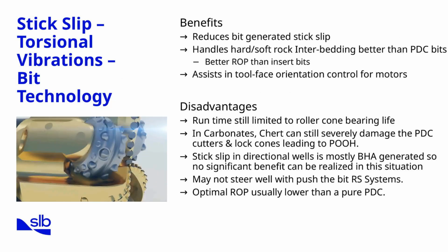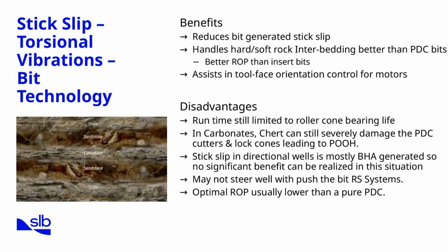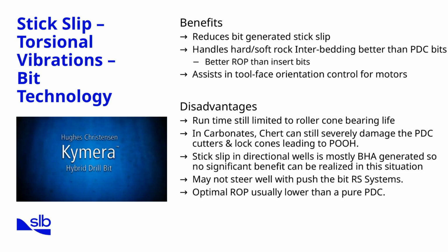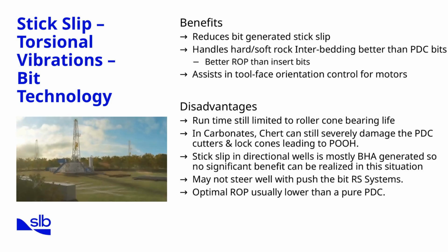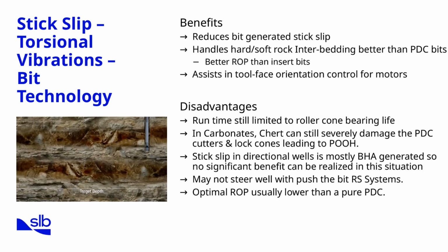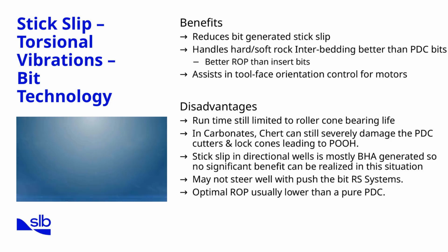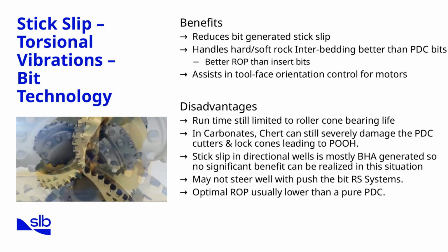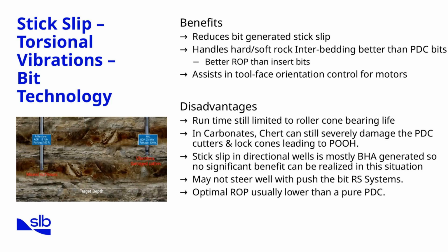First bit that successfully combines PDC and roller cone bit technology for smoother drilling, remarkable torque management, and precise steerability, handling the most complex well profiles and helping operators improve performance and profitability. With the cutting superiority and continuous scraping of diamond bits and the rock-crushing strength of roller cones, Chimera bits have the proven ability to survive highly interbedded formations with smooth drilling and excellent tool face control.